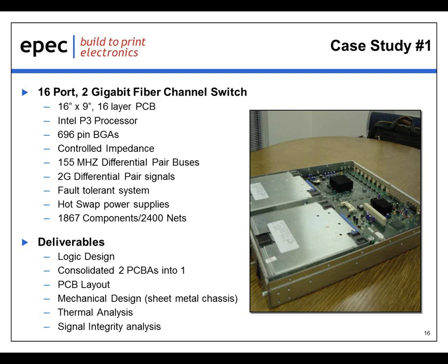And then we had to perform a thermal analysis. So you'll see the power supplies, the airflow was from right to left. The power supply sucked in air over the PCB and it expelled it on the left through the left-hand side of the power supply.